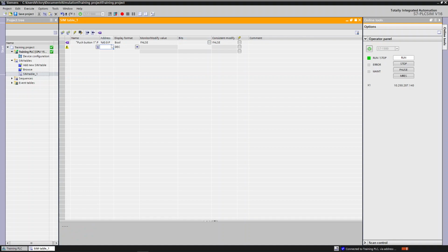For an integer tag, IW, we have a valve, and this is an integer tag. Here you can move between the ranges, minus 32768 to 32767, and the value changes. But if it's boolean, you could just click true, monitor, toggle the bit, true or false. So this is just PLC SIM, what you use to simulate a project.